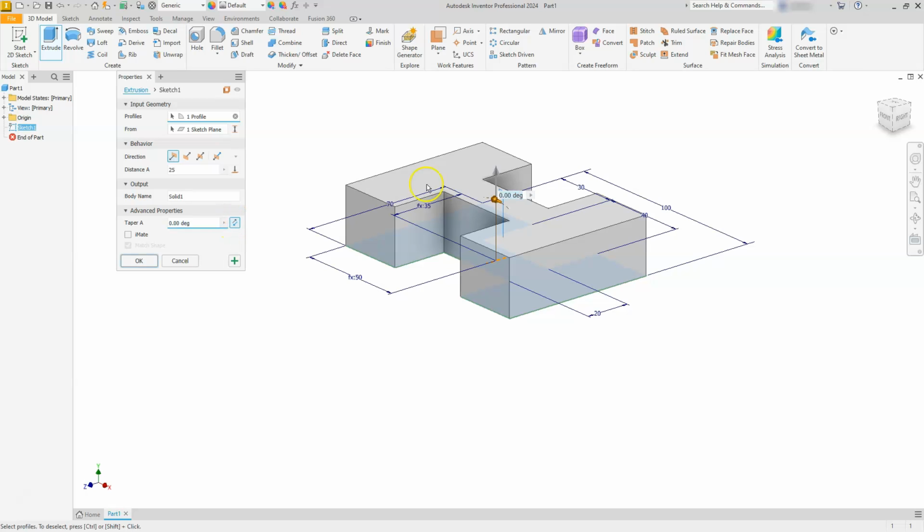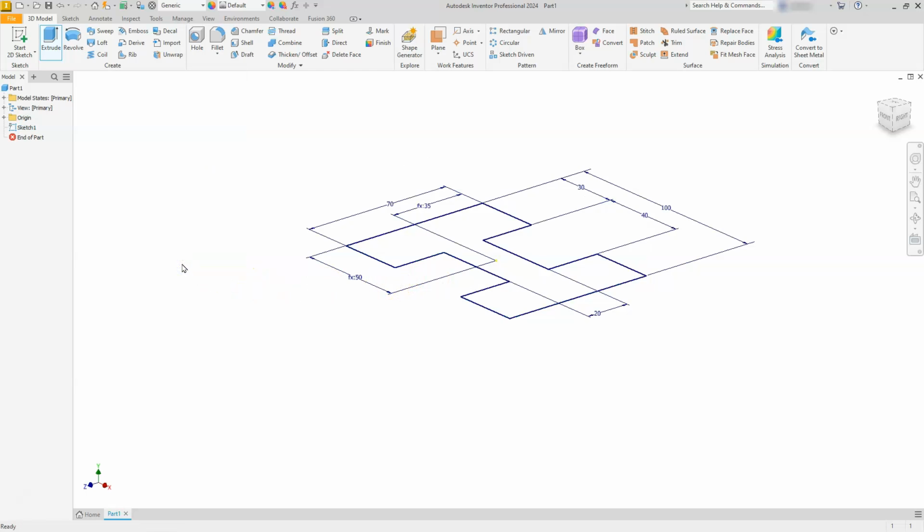So I could try to change the direction and see if it's going to fix this. Now that I just thought about it, it's going to be hard to taper this with the sharp corner. So that's going to lead me to go ahead and put the fillets in before the actual command. So let me jump back to the sketch, and then I'll put the fillets in, and then this should work well. I was trying to show you the multiple fillet command, but this is not really a good example to do it in. So I'll go to cancel.